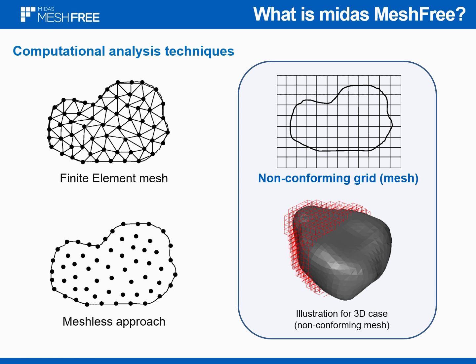These days, auto-mesh generators have been developed that work acceptably for most 2D problems, but can still deliver unreliable results for some 3D geometries, and they often result in poor or distorted elements in some regions that can lead to large error in the solution. A significant amount of user intervention is still needed to correct such problems.